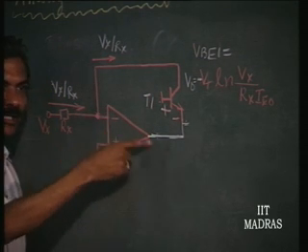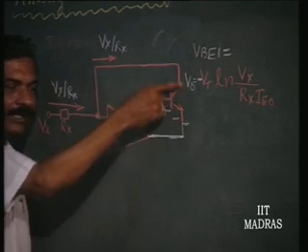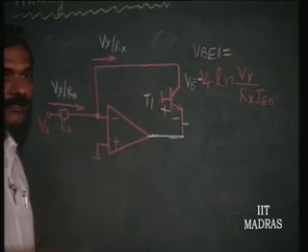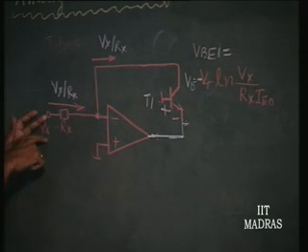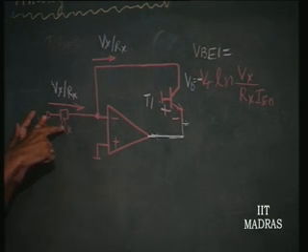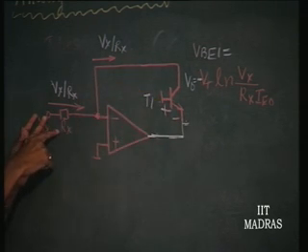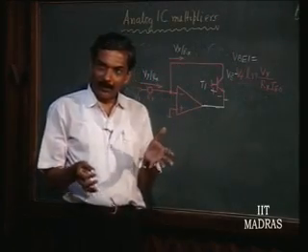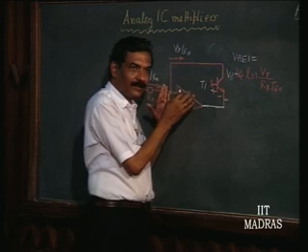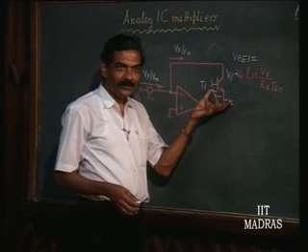This is an inverting amplifier, here to here, and then you have a transistor amplifier in common base, which has, if you ground this basically, a gain of its gm, which is 1 over re, times Rx, and that output is connected to the op amp. That means the open loop gain of this, let us say, is A, that is to be multiplied by gm into Rx.